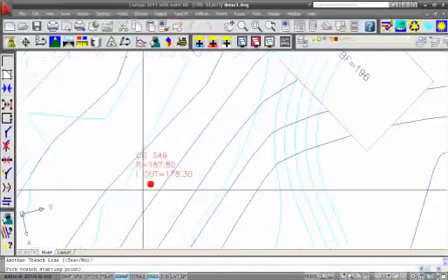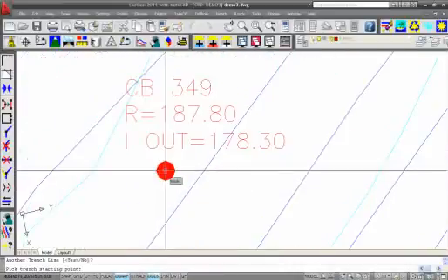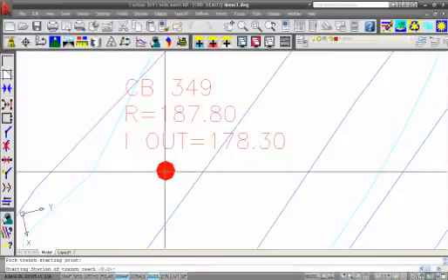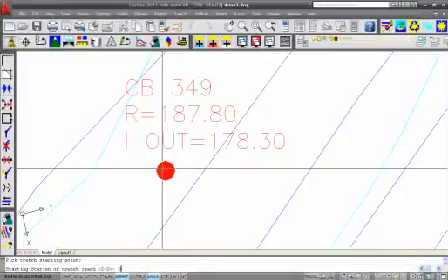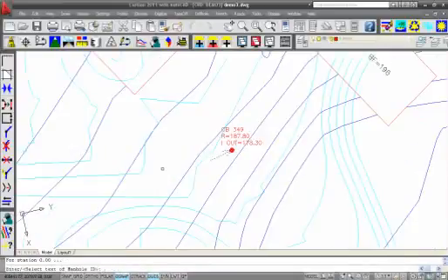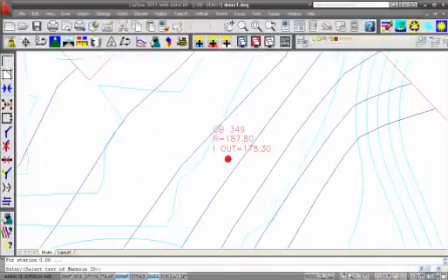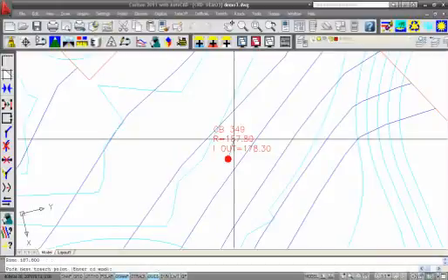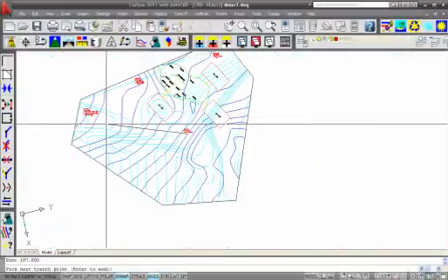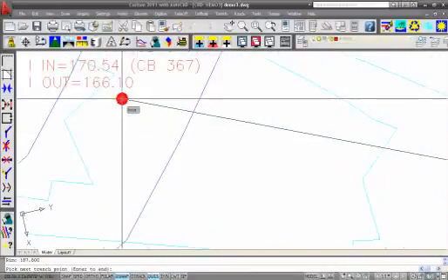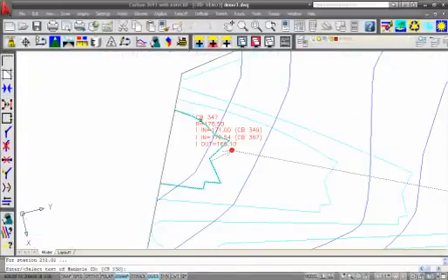and we have one more down here. And just pick this point, starting station 0 on this as well. Manhole ID, the invert out and invert in, same. Rim elevation, and then I'm going to connect back up over here. Okay.